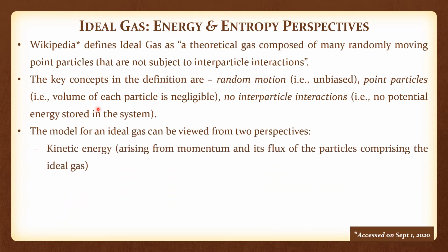One is from the kinetic energy perspective. This is from the transport picture, arising from momentum carried by the particles and the momentum flux of the particles, which should lead to pressure, right? So we saw in the development of the continuum model of a flowing fluid that the convective momentum flux is essentially pressure.